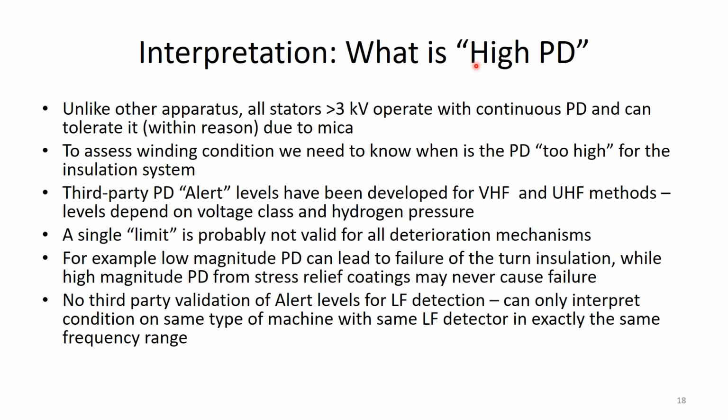Okay, so high PD, in the beginning, if you read some of my papers in the 1980s and early 1990s, I didn't think we could ever actually determine whether a machine was good or bad based on PD levels. That was based on the theoretical knowledge of how PD manifests, and how it gets from the stator coil to the machine terminals. But eventually we were doing enough analysis, and I have a colleague of mine, Vicki Warren, who still every 2 years does an analysis of our database, and I'll show an extract of that in a few seconds.